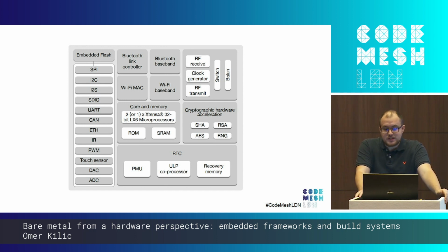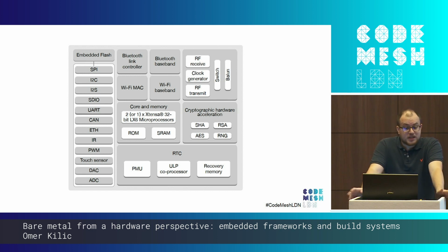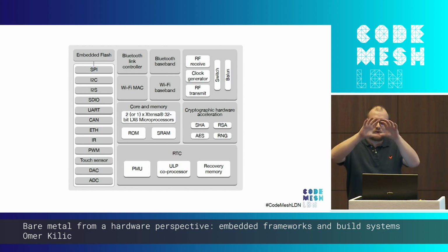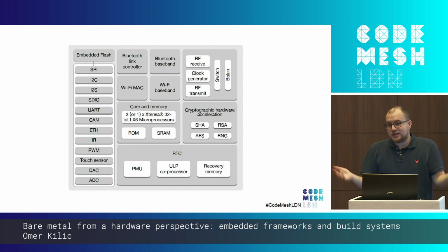So instead, you have things like I2C, SPI, GPIO, etc. And as part of the whole package, usually you have some support components, like, say, some cryptographic accelerators, an RTC to keep track of time, because if you don't know what time it is, then you're probably going to have a bad time negotiating SSL. And usually there's a black box of an RF blob somewhere that does something that you never know what goes inside. It's the blobs that we were talking about.